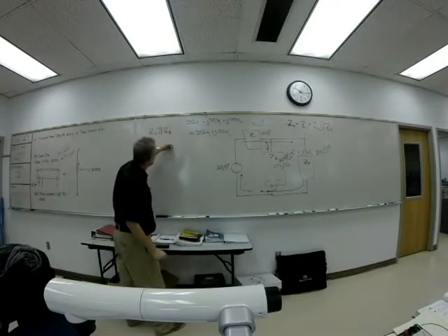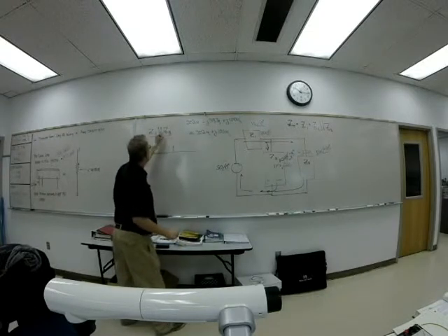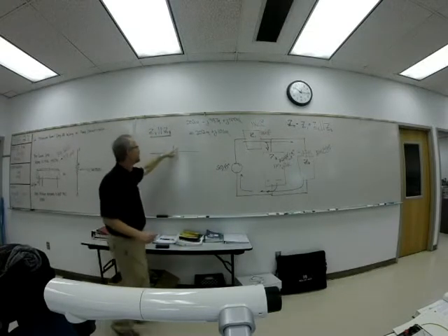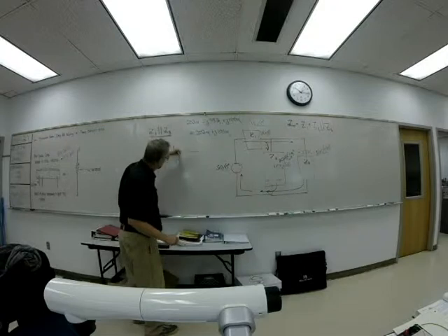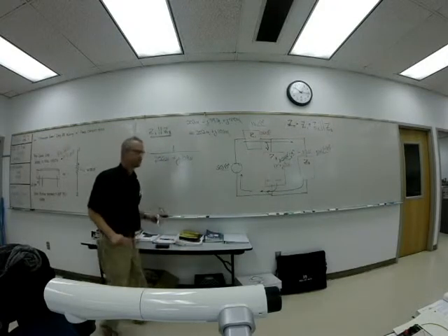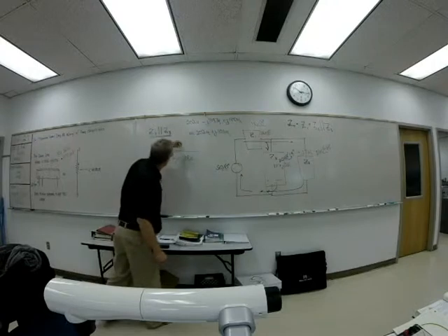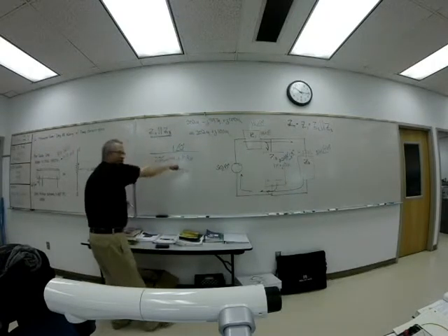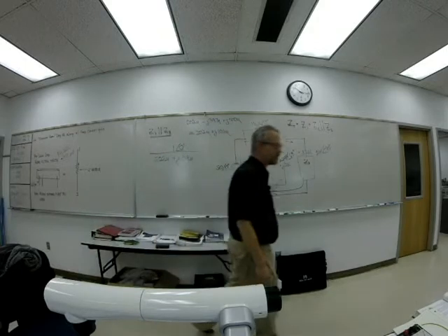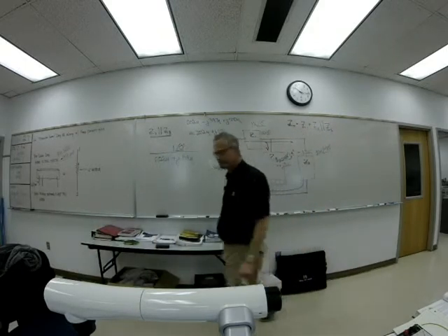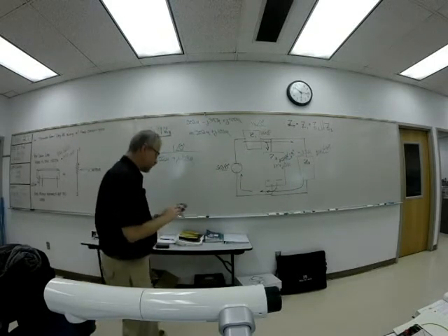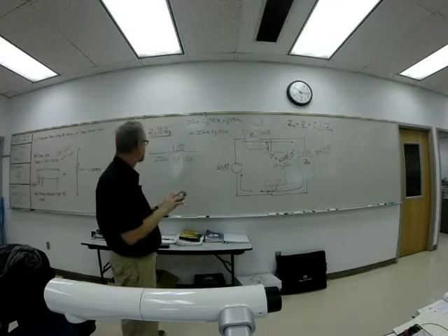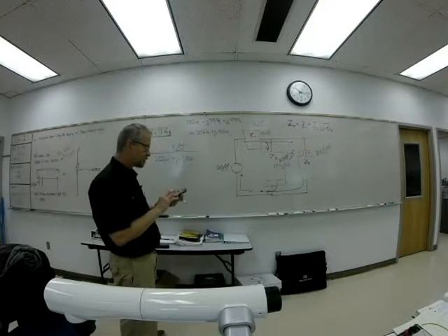Okay, so we are sitting here right now trying to calculate Z2 in parallel with Z3, and we are now at this point. And this, of course, is 1 at an angle of 0. We need to convert again, back to polar. Second function, 103, second function, rectangular to polar.